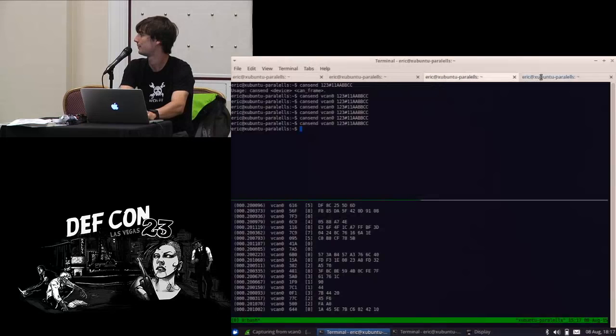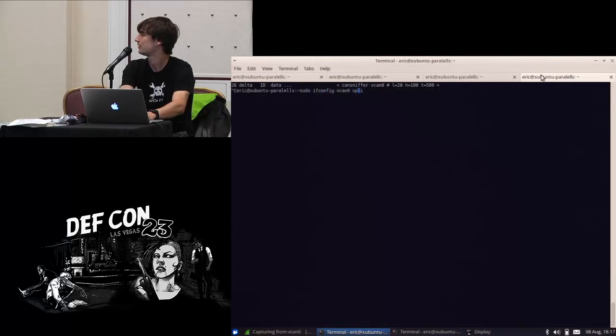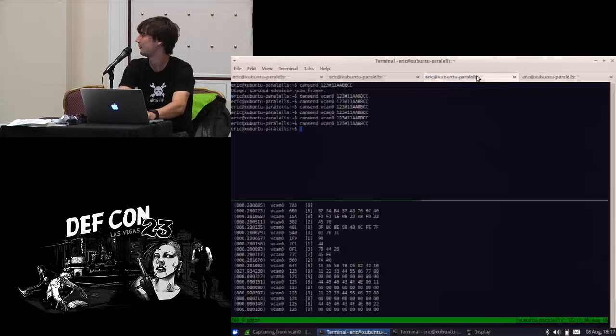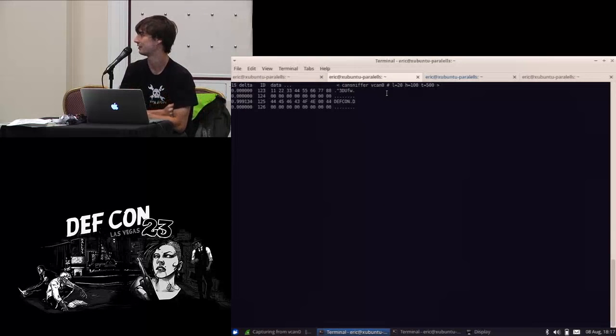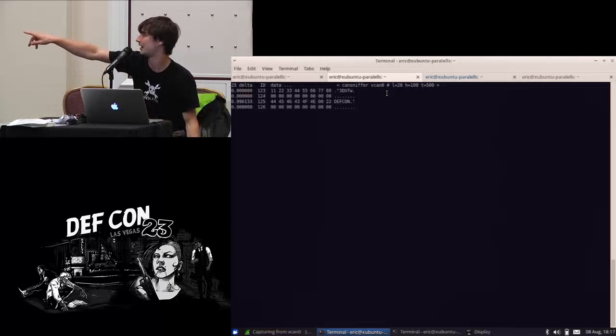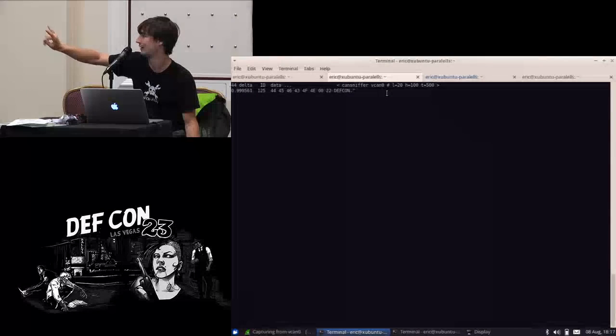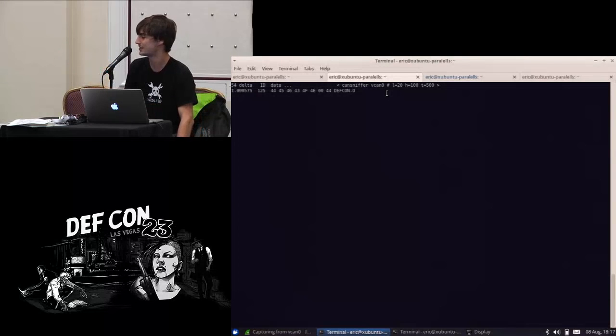Oh, I've killed off all of my messages. One sec. We'll start that log up again, and we will go to here, kill that. CAN sniffer vCAN 0. This is going to show you everything going on the bus. You see a bunch of messages at the top. After a couple seconds, a lot of them go away, and we only have one left. And the reason being, this is the only frame where anything is changing. Everything else, we're just getting the same frame, the same data over and over and over again.